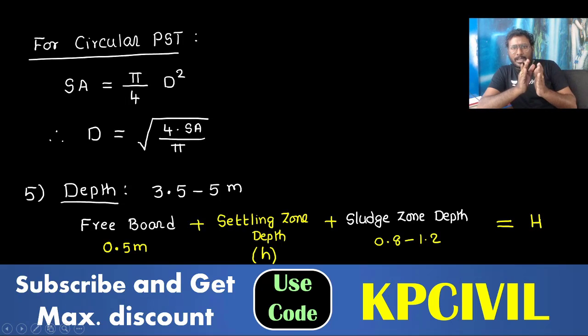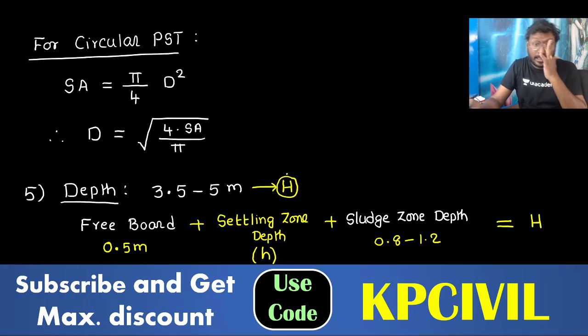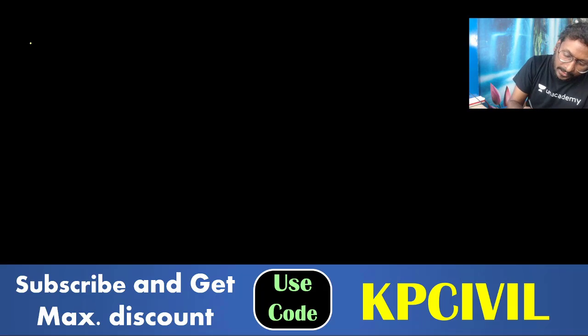So finally the total depth of the sedimentation tank, capital H, is equal to freeboard plus settling zone depth plus sludge zone depth. All three combined we are taking as 3.5 to 5 meter. That is 0.5 meter plus small h plus 0.8 to 1.2 meter. Total depth capital H we are considering. Okay. So we got the dimensions L, B, H, or the dimensions capital D, the diameter of the tank, under H. What will you get finally?